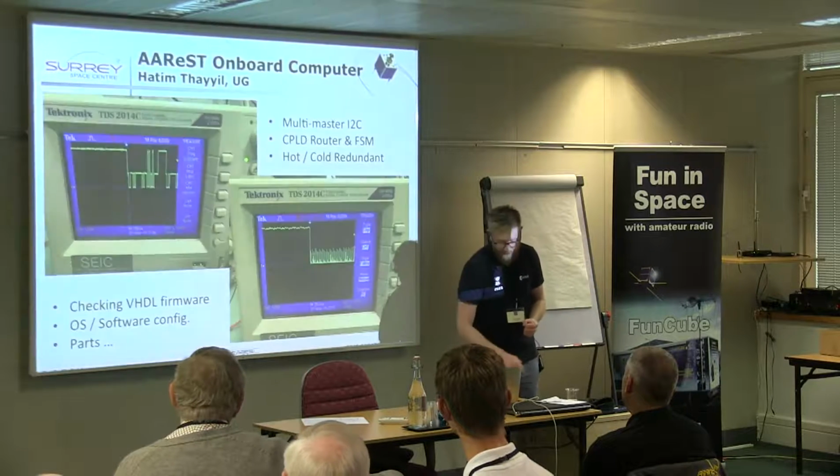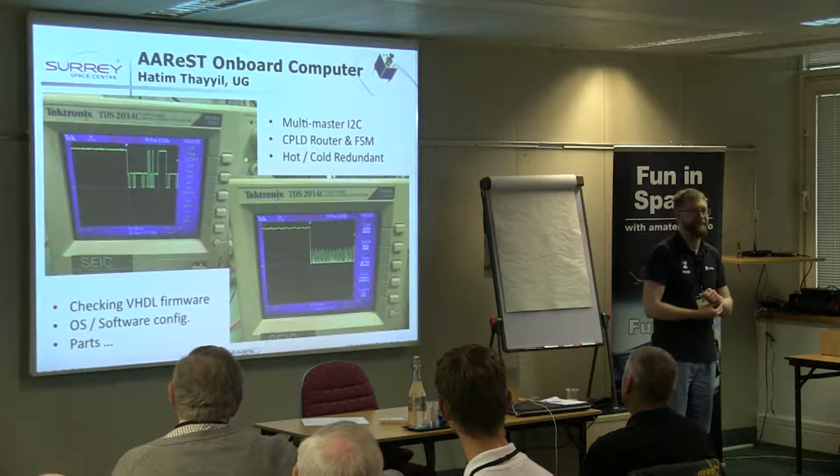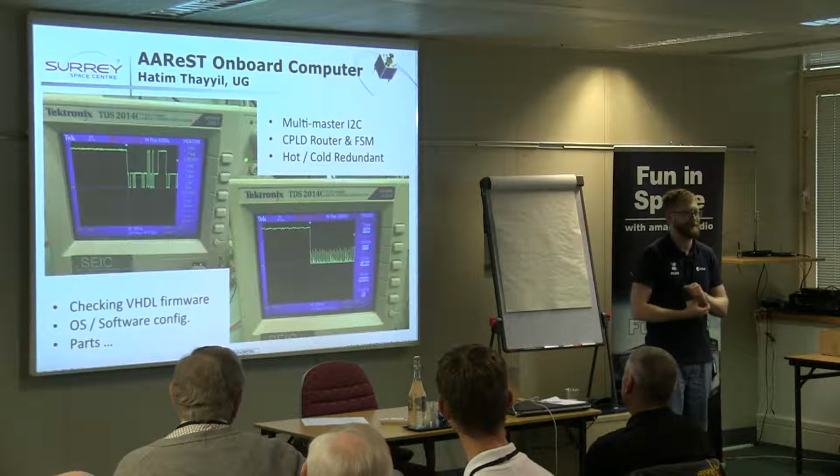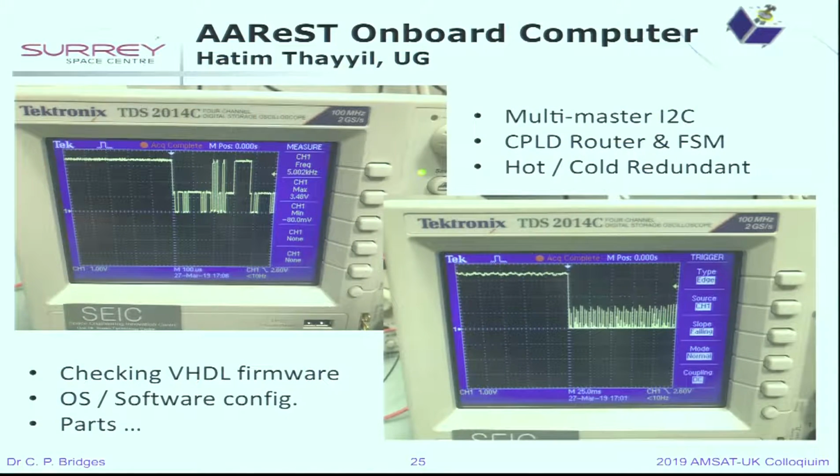And her team essentially was figuring out how I2C was working, really from a 101 point of view. For those of you either on the stream or in the room, who know, love, hate, pick your relationship with that particular data bus, will have seen many of these diagrams before. As I said, our CPLD has multi-master I2C. We have a payload I2C bus. We have our own platform I2C bus. And we use these things to route information very quickly between a lot of the modules.